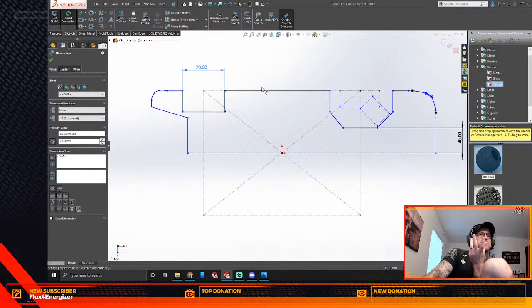We can always put wider tires on the back. But we also want to make sure we have enough room for the rear diffuser to expand the air that's traveling underneath the car. So what we can do is cut it short.